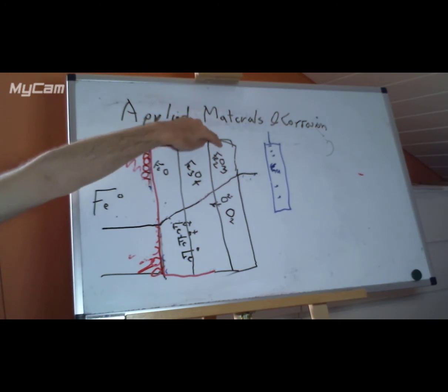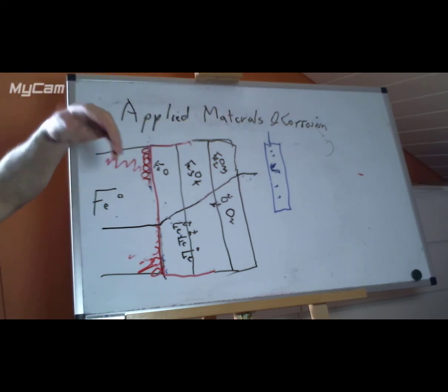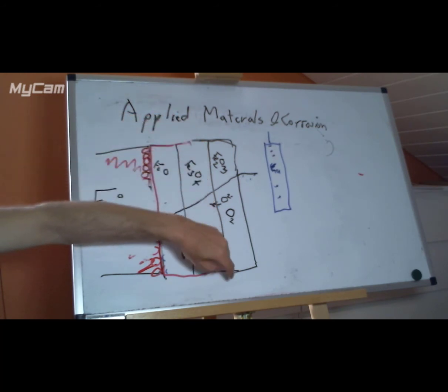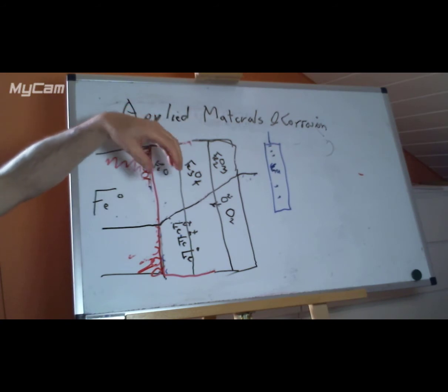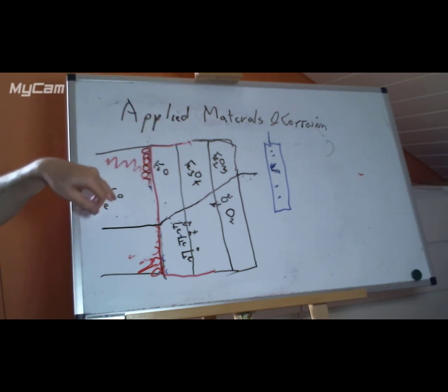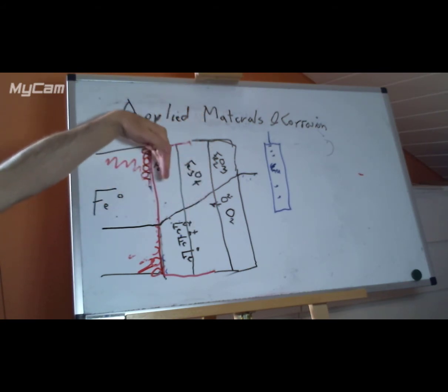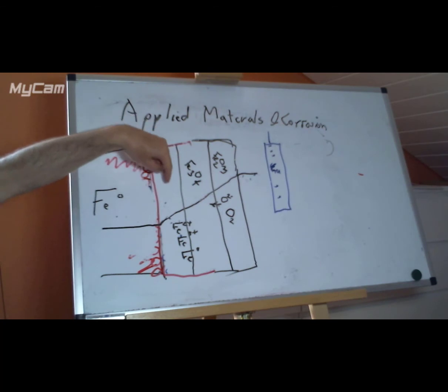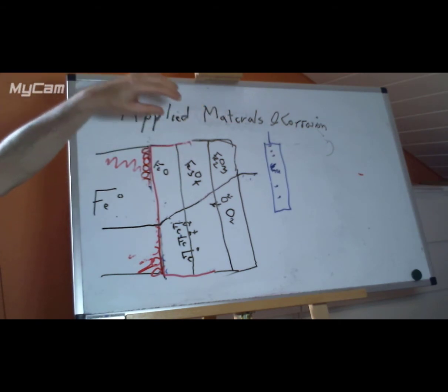And on the surface we've got Fe2O3, which is iron(III) oxide. In reality, there isn't a strong border between these because there are other states. But depending on what the element is, what the metal is, we could end up with borders in between where we would see a phase boundary, because the crystal structure of these are different.